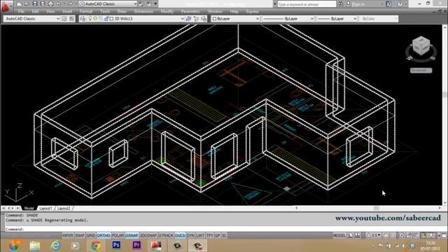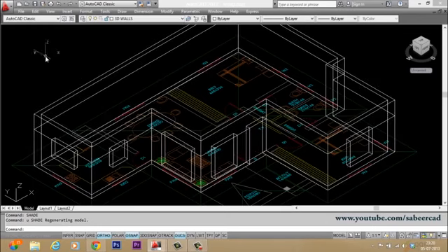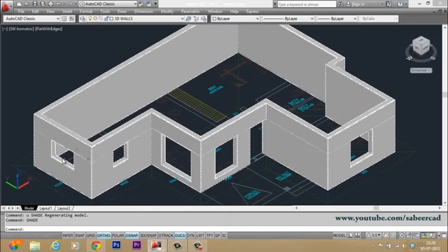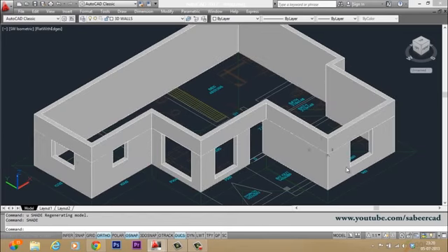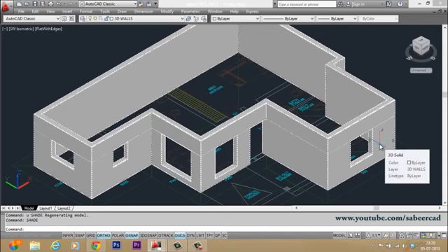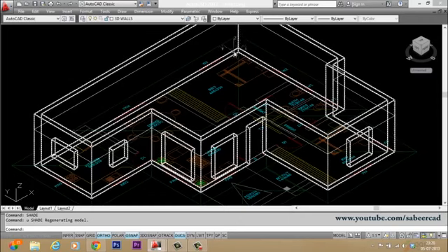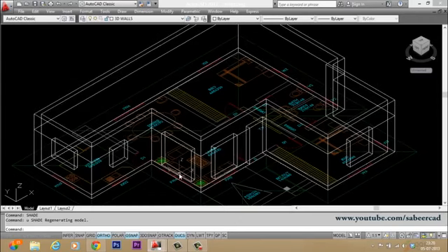And by the time you complete creating cutouts on respective window and door locations, your 3D model will appear like this. Now let's shade the model. This is how it will appear. Now you can see that you have created cutouts for the doors and windows only on these sides, because I actually want to create a southwest view. So even if there are doors and windows on the other sides, you don't have to model or create those windows because those objects are not going to be captured by the camera.